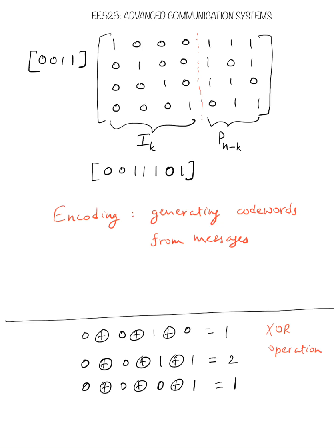What you saw today is a slightly more advanced topic than the parity codes. The parity codes that we saw earlier were just error detection codes, which can only detect errors, and even then they can detect only an odd number of errors. If there is an even number of errors, they will fail to detect them. Now we have seen today how to construct the code words for a 7/4 Hamming code using a generator matrix.